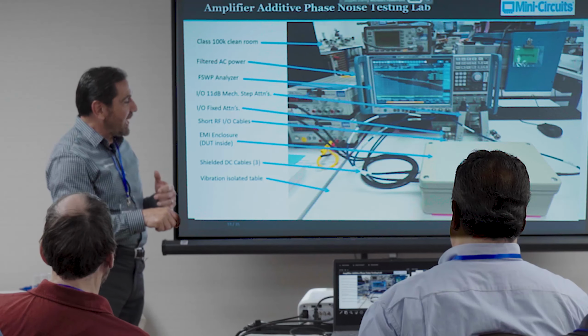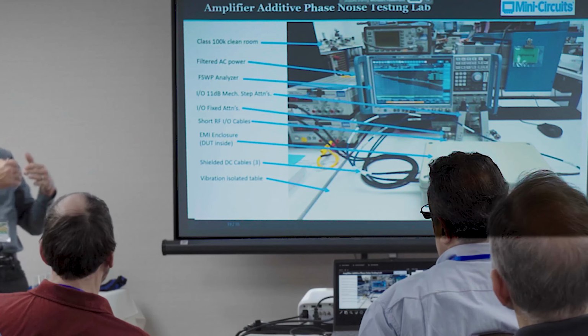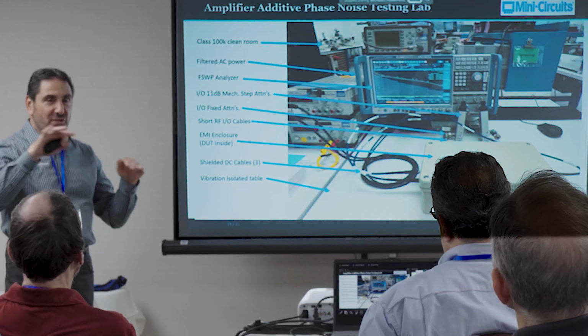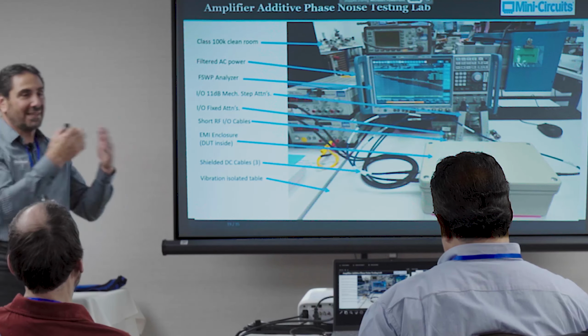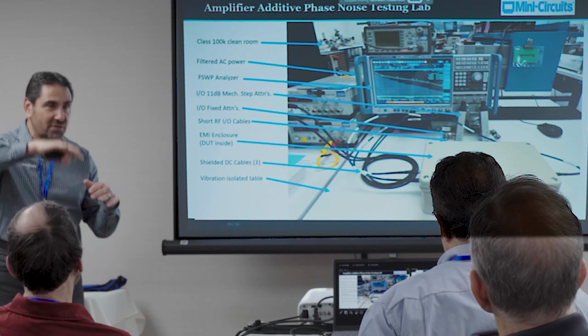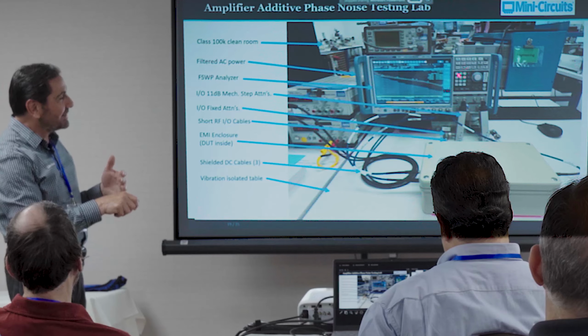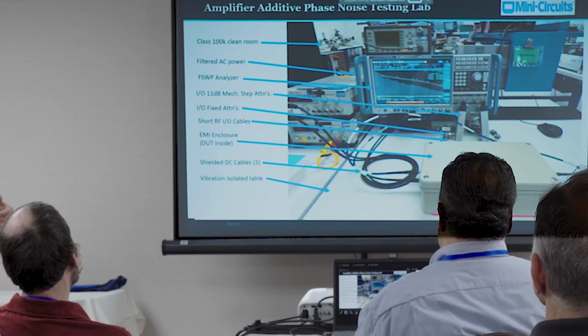And the same thing now, the output power of the amplifier goes back in. We use this to make sure that we always get about the same level back into the instrument. So we're always measuring at a consistent range of output power, and we use the attenuators to set the input power. So we don't see the strange peaking effects that you sometimes get by using the attenuator in the instrument. I don't know if yours does it, but awesome.